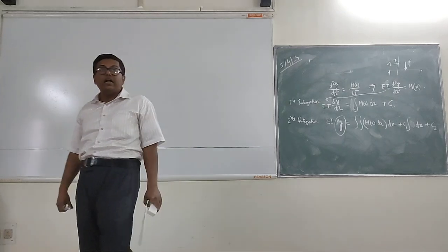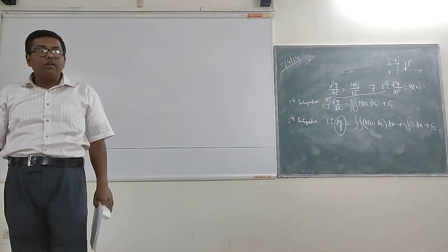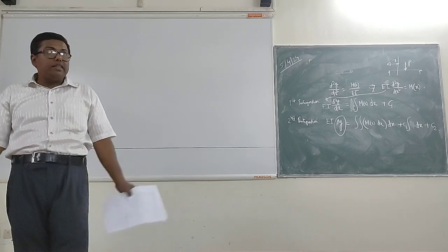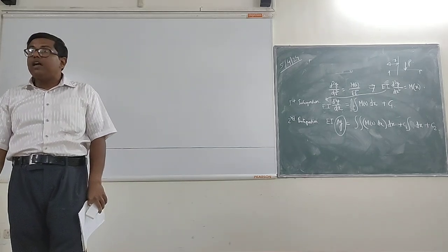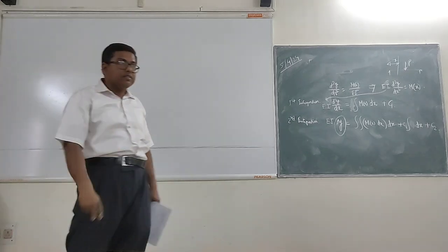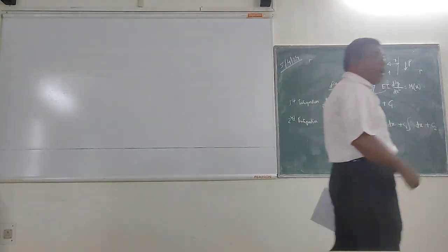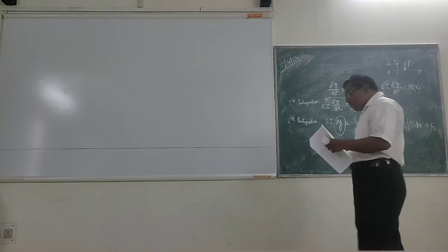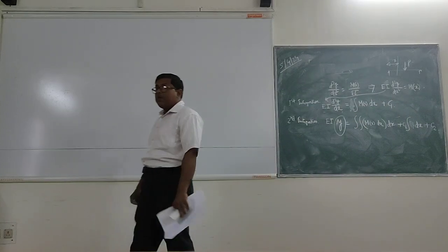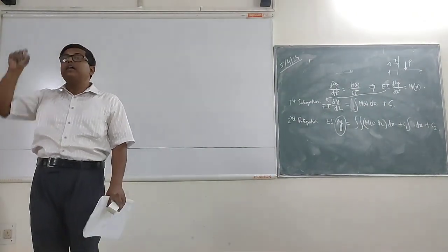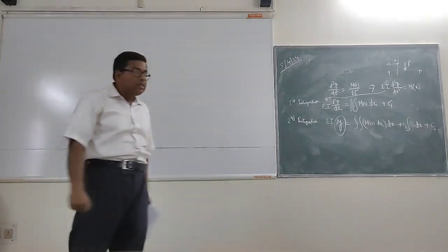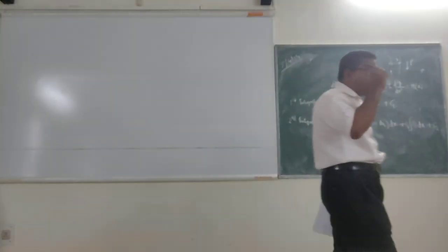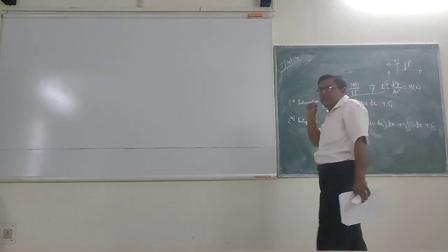So if this equation doesn't help in that case, correct or not? So the equation is established that we cannot find the deflection from it because there are two unknown constants, C1 and C2. So from where I will get that C1 and C2? This is another very important thing you should understand, that C1 and C2 are to be found out from the boundary conditions. Boundary condition means, for a typical type of support condition, just to initially understand boundary condition.